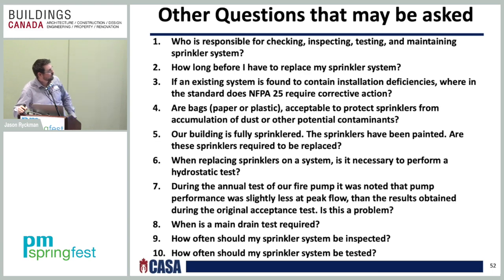When replacing sprinklers on a system, is it necessary to perform a hydrostatic test? The answer is yes. If you have to replace sprinklers on your system and there are more than 20 sprinklers, you have to do a hydrostatic test. That would be in the installation standard, since you're taking out the sprinkler head and reinstalling it. It stipulates that if more than 20 sprinkler heads are replaced, you have to hydrostatic test it. Also, if you do replace a sprinkler, it has to be a new sprinkler. You can't reuse sprinklers.